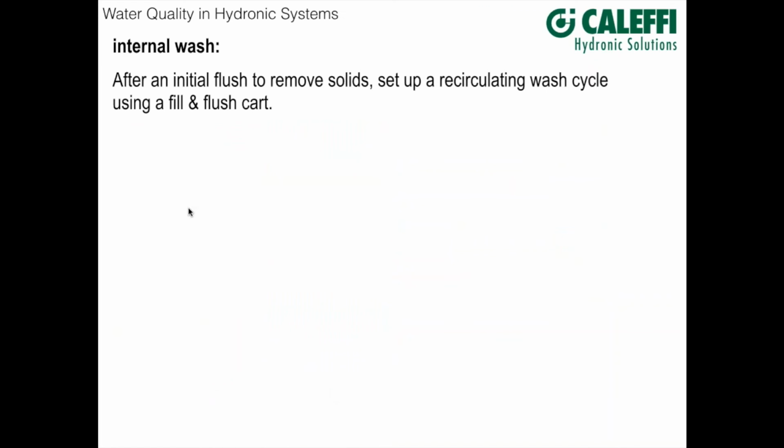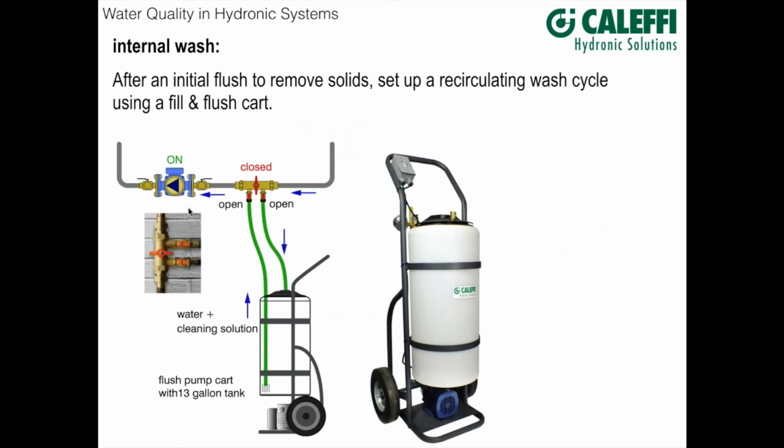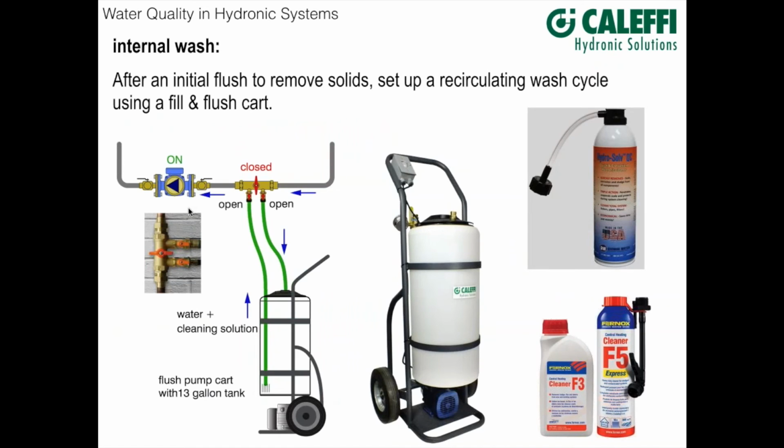Okay. So after we've flushed the solids out, we want to do an internal wash, and this wash is set up to chemically clean the inside of the system. And again, Caleffi has a flush cart that's available, and there are products on the market. I've just shown a couple of them over here by Romar and by Fernox. I call these hydronic detergents. They are designed to dissolve the oils and the fluxes that would be commonly found in these systems.